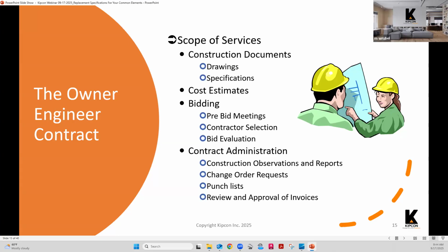We qualify this whenever we are asked to prepare an estimate. We say that the contractor bids you are about to receive may vary quite substantially from the estimate based on industry standards that we just prepared for you. So if you take those bid documents and go right out to bid with them, you are getting actual pricing from contractors. The cost estimate that's prepared has no bearing on what the actual cost of that project will be. The contractors are giving you their best cost to perform that work.